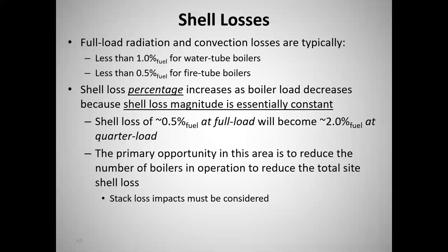That's much more efficient because those boilers making that steam are already operating well up in the load range, and they're more efficient. If you just intermittently fire a boiler, you're basically throwing that energy away just to keep the boiler hot. So there's better ways to keep boilers on hot standby than intermittent firing. But that's a little bit of a side issue at this point.